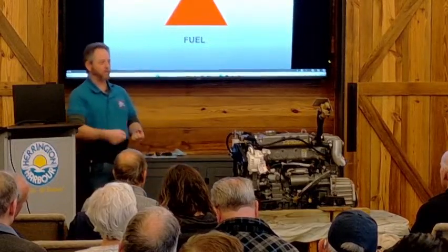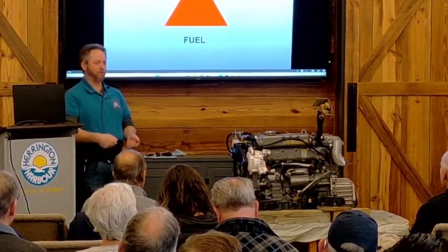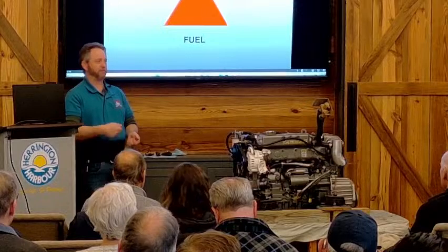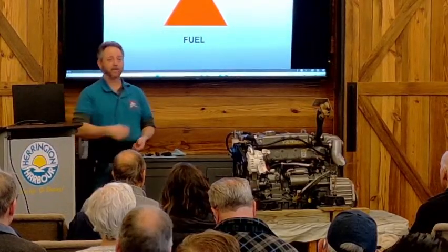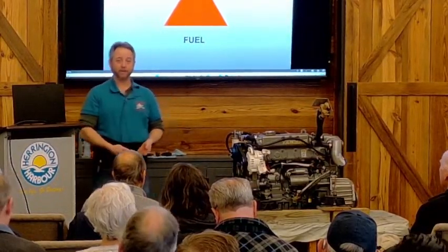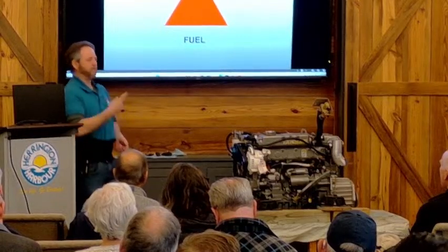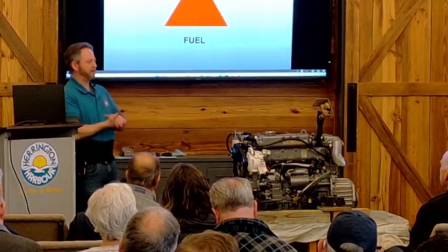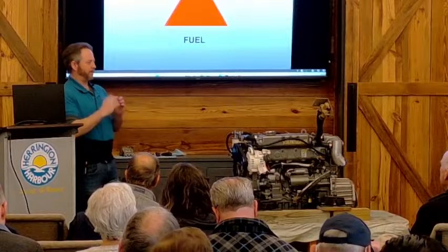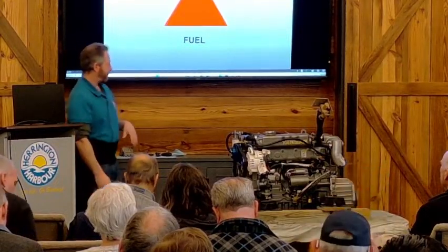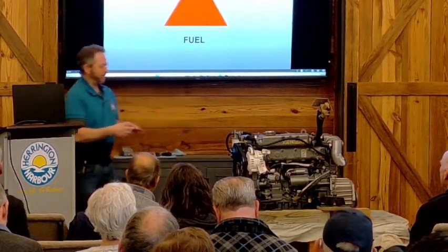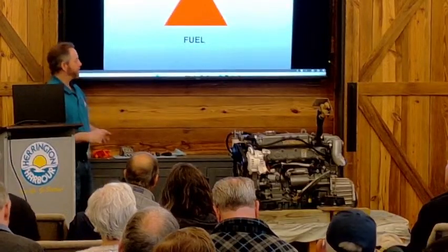It's got to be going rah, rah, rah, rah, rah, not slowly. You're never going to get a diesel engine started with a slow crank. So we need this engine moving quickly in order to create the compression and the amount of heat we need. So we need a good turning force.